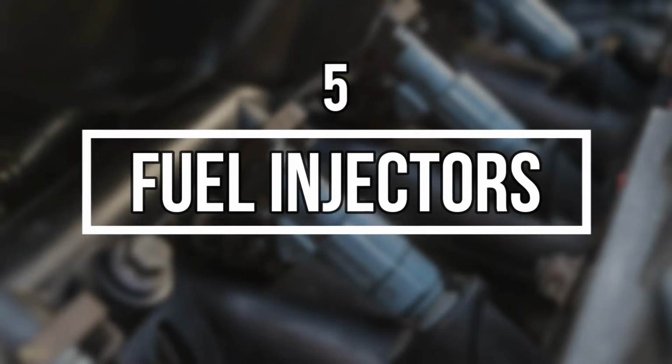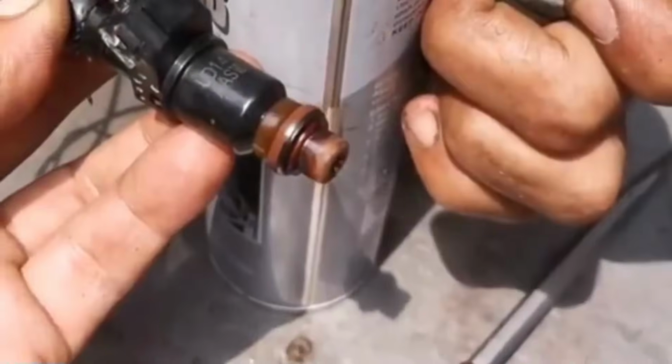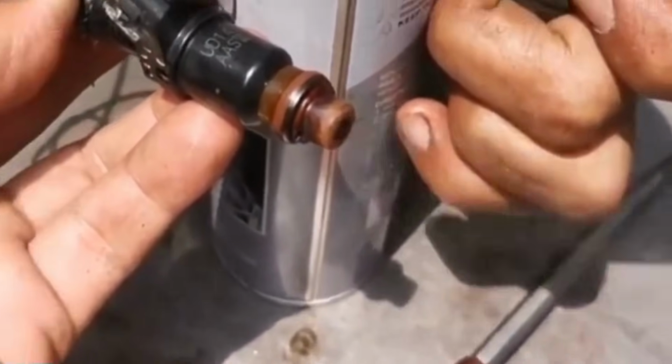5. Fuel injectors. Fuel injectors are the final component in the fuel delivery system. For proper combustion, fuel must be atomized into a fine mist as it exits the injectors. When injectors become clogged or damaged, a condition known as injector dribbling can occur, where fuel is no longer properly atomized. This results in excessive fuel delivery and increased fuel consumption.